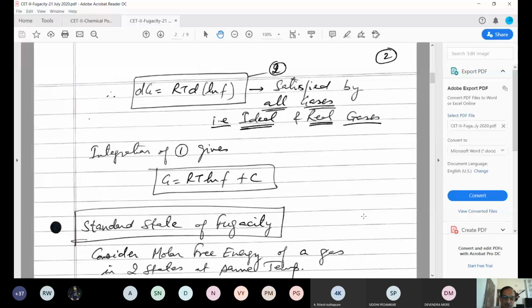So this is what we are talking about. We are talking about forces of attraction or repulsion between molecules or particles, and they increase. That's why the pressure increases. Right? I mean, pressure is representing the escaping tendency of the gas. The higher the pressure, the faster the gas will escape. Right? Because we saw P is a driving force for mechanical equilibrium. Like temperature for thermal equilibrium, pressure is for mechanical equilibrium. The higher the pressure, the faster it will transport.